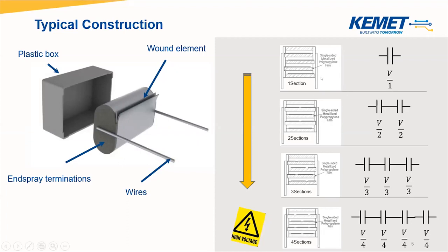So we said that the main and simplest schematic is the parallel construction, in which all the voltage is applied to the single layer of the dielectric. But we can have more complex constructions where we play a little bit with the metallization in order to create internal different sections to split the voltage across them.